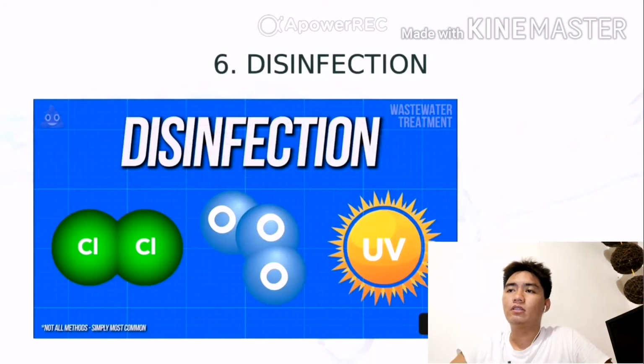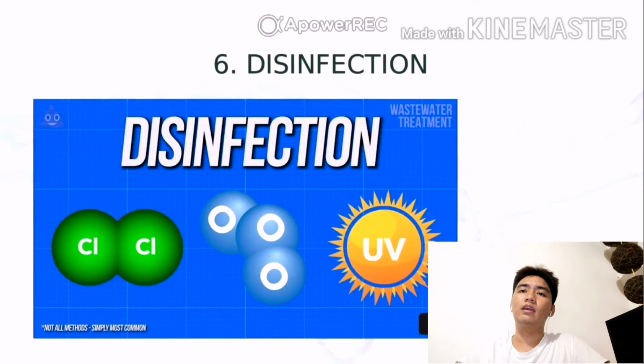Number 6 is disinfection. Disinfection is done to kill any remaining bacteria in the contact chamber. Disinfection could be either chlorination, ozone disinfection, or UV disinfection. Chlorination disinfects the water through chemical disinfection, and chlorine is removed before it can be discharged to the environment.